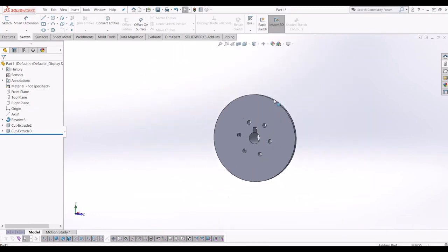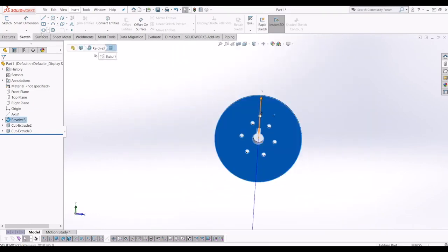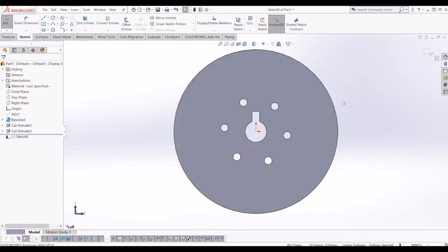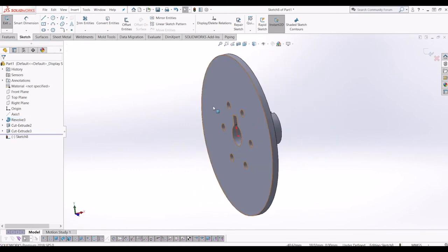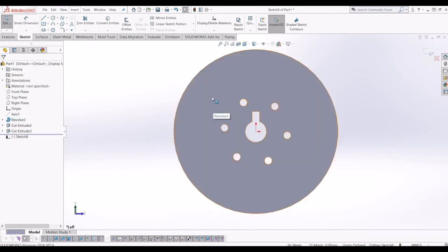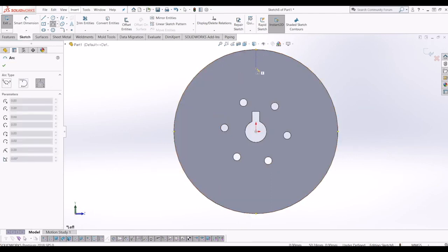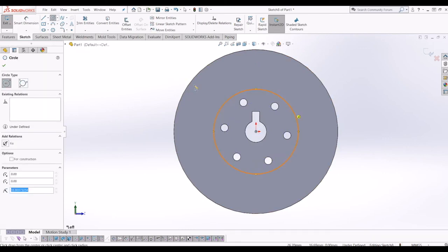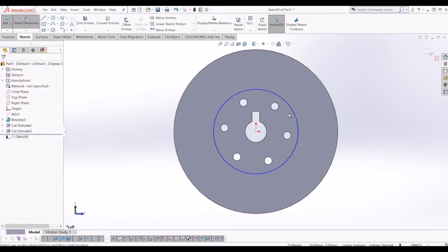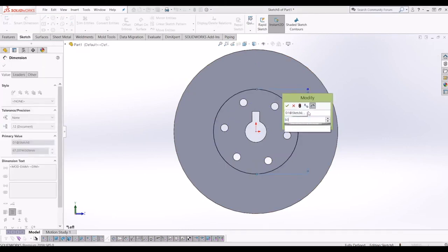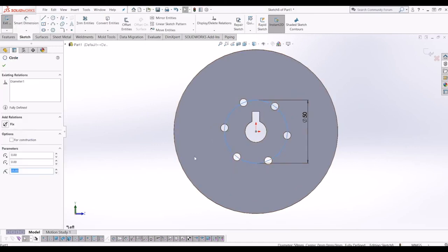It's now time to draw on the impeller blades. To do that, draw a sketch on the front plane, on the front of your impeller disc. Now, if I draw 2 arcs, in fact, let's draw the guidelines first. So I'm going to draw another circle, 50mm in diameter, and make that a construction circle.